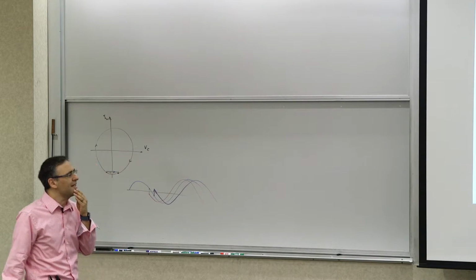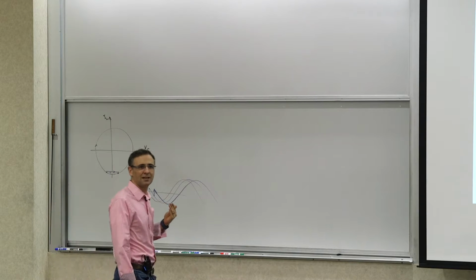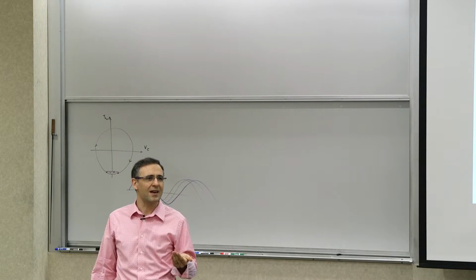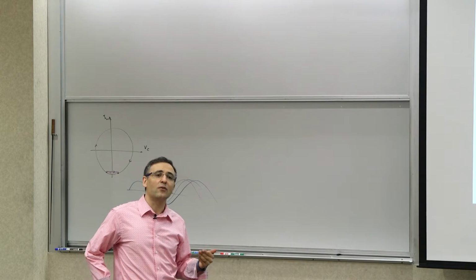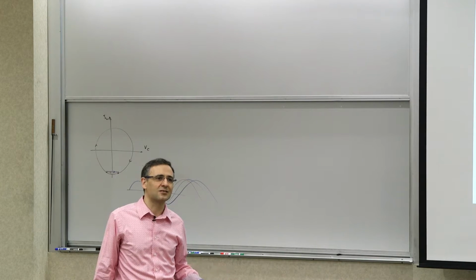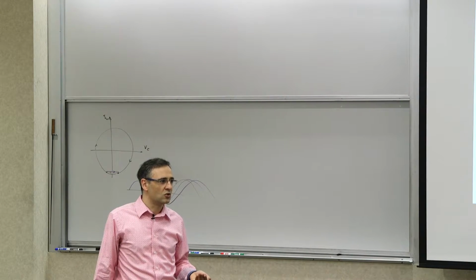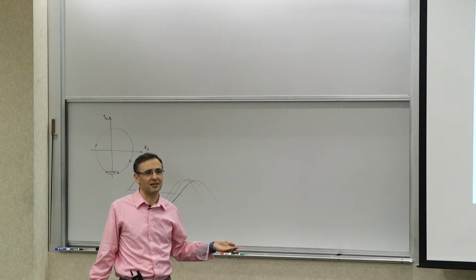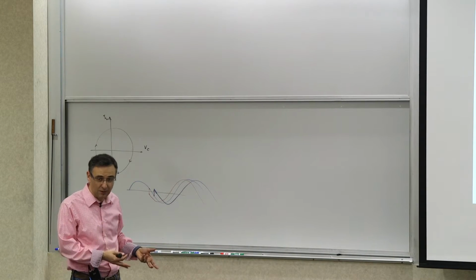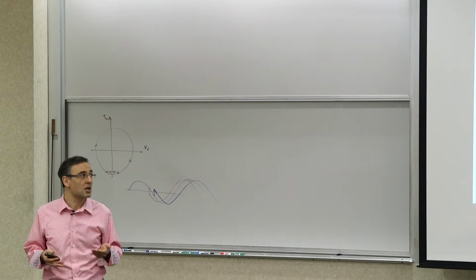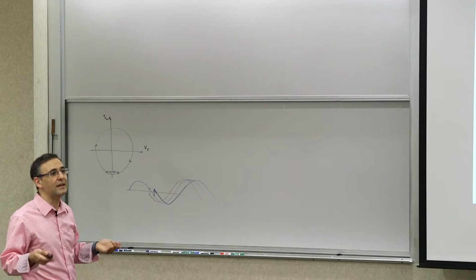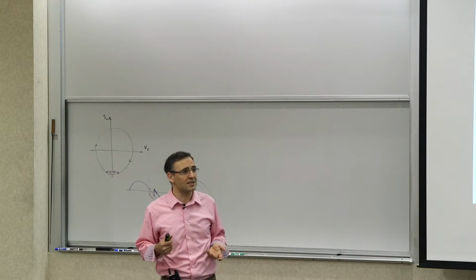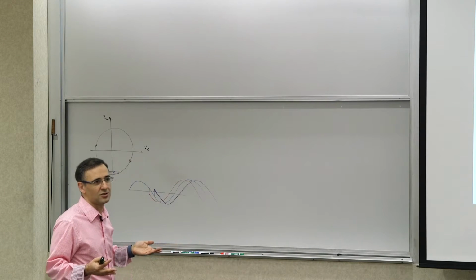And you may come back and say, wait a second, this is an LTI system. How can it be time-varying? The capacitor and inductor are LTI. How did you get a time-varying system from this? Well, they're LTI for voltages and currents. They're not necessarily LTI for other variables. If, for example, I determine the temperature as the output, would it remain LTI? Not necessarily. So it's a function of not only the components, but also the choice of the input and output variable. Now the output variable we are looking at is phi, the phase, not a voltage or current, and hence it's OK for it to be non-LTI. In fact, in general, it's not even linear for large perturbations.